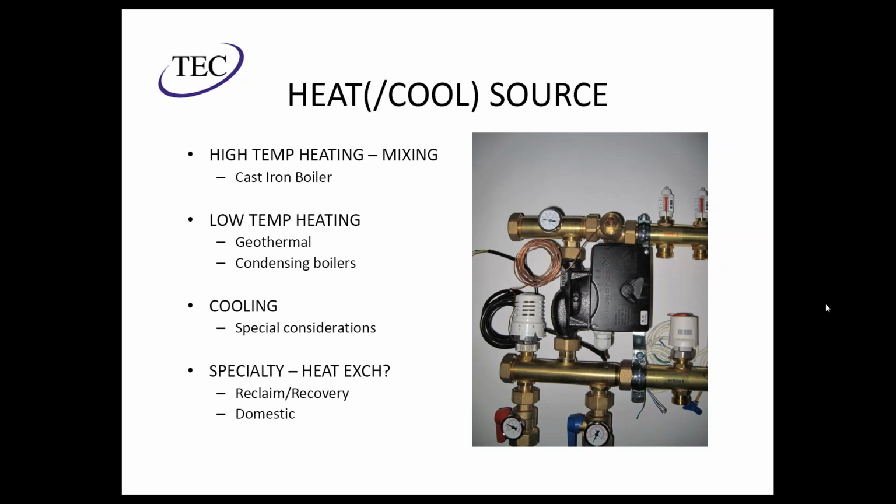You're going to need a chiller or a geothermal loop to supply that, and you're going to have to plan accordingly. And there's certain specialty applications, using heat reclaim on chillers, or using a side arm on a domestic if it's a really small zone, or wood-fired boilers. Those are all applications. Anything you can warm or cool water with can be applied here, but you just need to make sure you're taking the appropriate steps to protect the slab from extreme temperatures and protect the heat source.